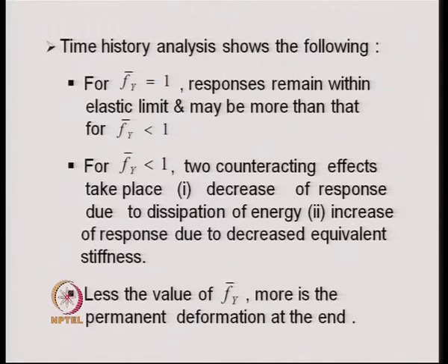As the single degree of freedom system goes into the inelastic range, there is a dissipation of energy because of the hysteresis loop that is formed because of the force deformation behavior of the system. And second, since the system goes into the plastic or inelastic state, its equivalent stiffness is decreased.